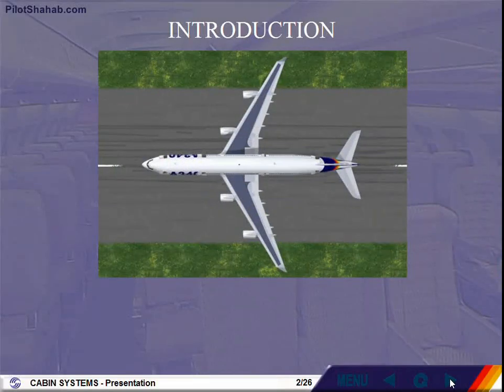Basically, the A330 A340 aircraft family is equipped as follows. Type A doors at exits 1, 2, and 4. Type 1 doors at exits 3. In this configuration, the maximum number of passengers is 375, with a minimum of 8 cabin crew.